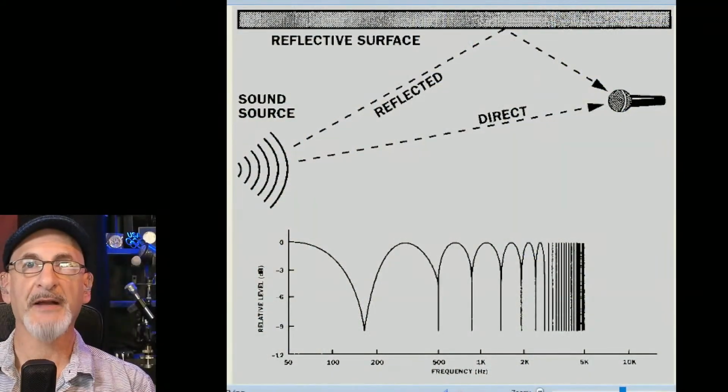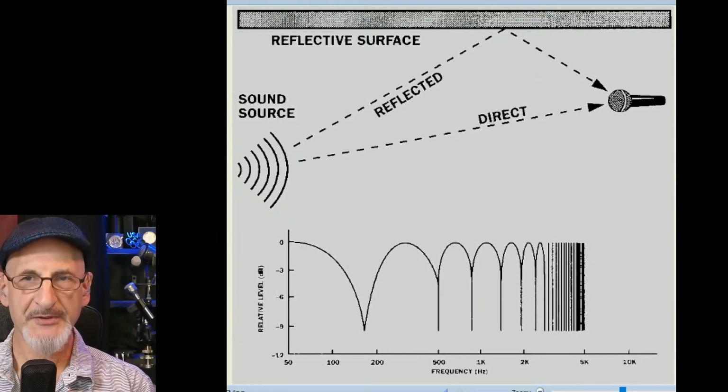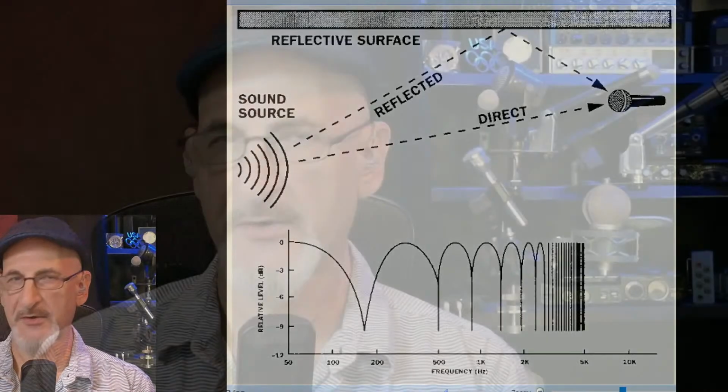So you have direct sound and reflected sound. And the microphone doesn't know that the reflected sound is related to the intended sound, and so it cancels it out as well. And that's when you get comb reflections and hollow sounds and all kinds of nasty things.